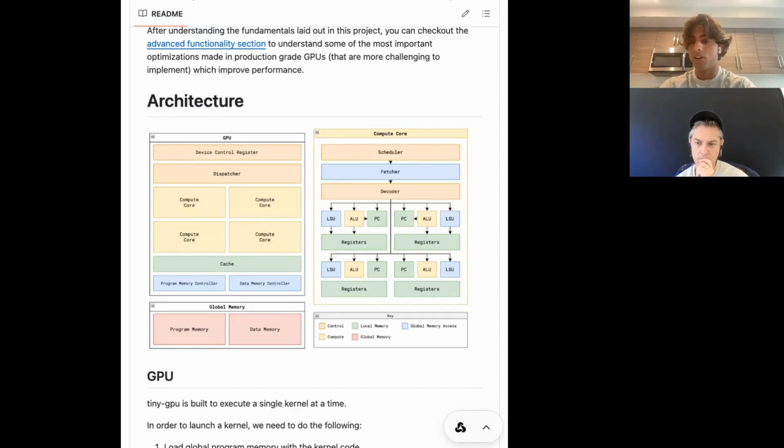First of all, you have the actual kernel code. And that's, as we wrote below or before, just a bunch of instructions. And those instructions happen to be written in assembly, which is a nice verbal format for us to visualize them. In reality, we would compile that assembly, pretty standard stuff, into object code, which is specified by the ISA. So it's just going to be a bunch of ones and zeros, all 16 bits long, and load that into program memory. So now, let's assume we've loaded that into program memory. Let's say it's 12, 15 lines long. So now we have our kernel code loaded up into program memory, and that's just going to specify exactly what our kernel is, just in bits.